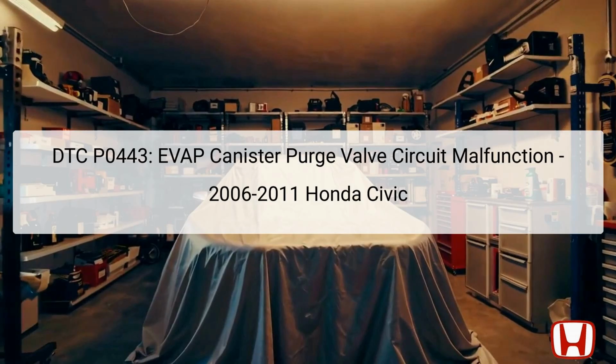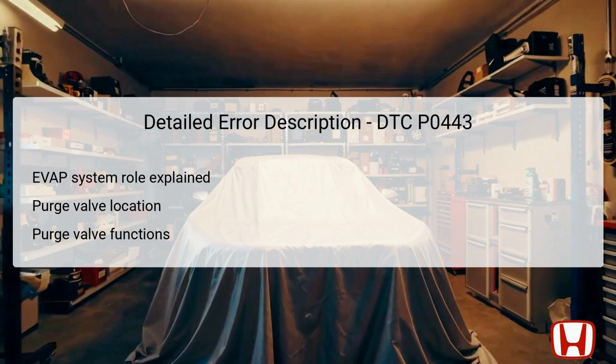Diagnosing this requires specific tools like a vacuum pump and gauge. Before starting any repair work, it is crucial to record freeze data and review general troubleshooting information to diagnose the issue effectively. The EVAP system plays an essential role in controlling evaporative emissions from the fuel tank.